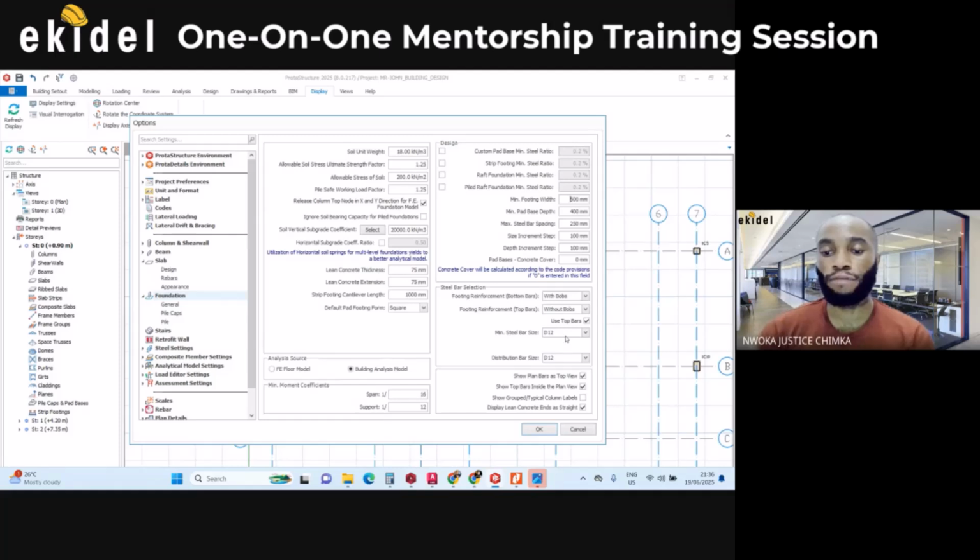Then you can see a minimum reinforcement. This is for general, both for pile and everything. So now here it is saying 12 minimum, and then distribution bar still 12 minimum. I think in your country, for pile foundation, you can use 12 at least. Minimum should be 16 based on the length it's going.